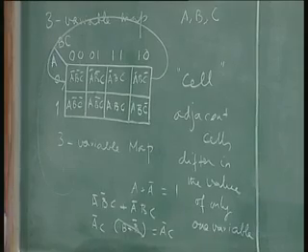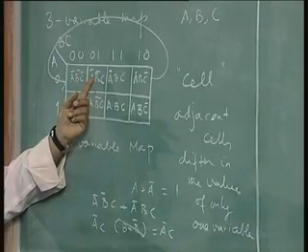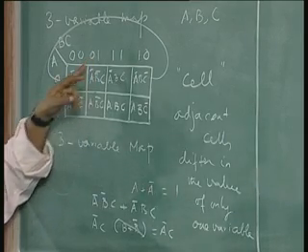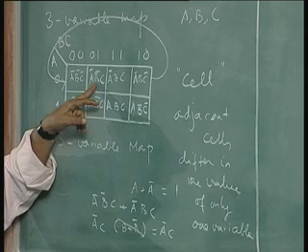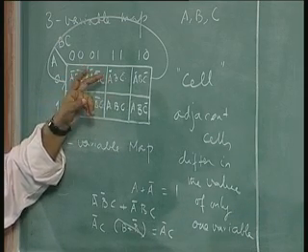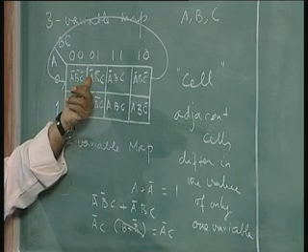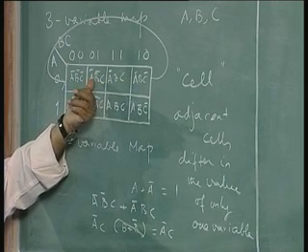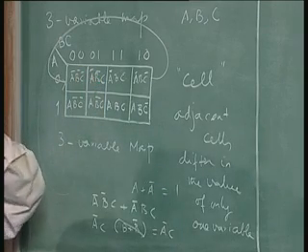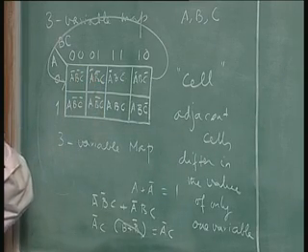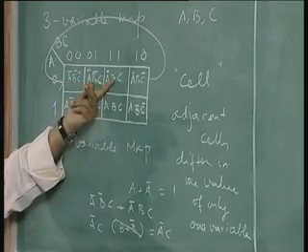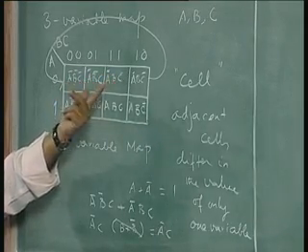So, what does it mean now? If I have a value whose output is 1 or true for this case and for this case, that means the truth table will have a 1 in this cell as well as in this cell. When I have 1 and 1 in two adjacent cells of the truth table, I can knock off the variable which is different between these two cells and have a simplified expression. That is what we did.